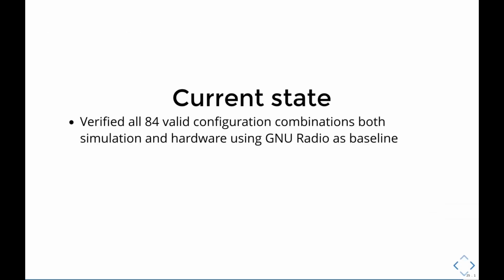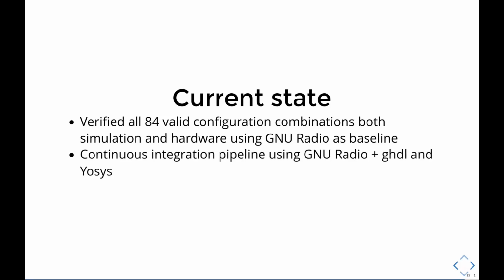We have verified all 84 valid configuration combinations in both simulation and in hardware, using GNU Radio results as a baseline. And this includes varying configuration on a per frame basis. We don't need to stop data flow, change parameters, then restart, although there are some caveats. We also have a continuous integration pipeline running on GitHub that runs tests on GNU Radio plus GHDL and some tests with Yosys. If you're not familiar, GHDL is an open source VHDL simulator, and Yosys is an open source